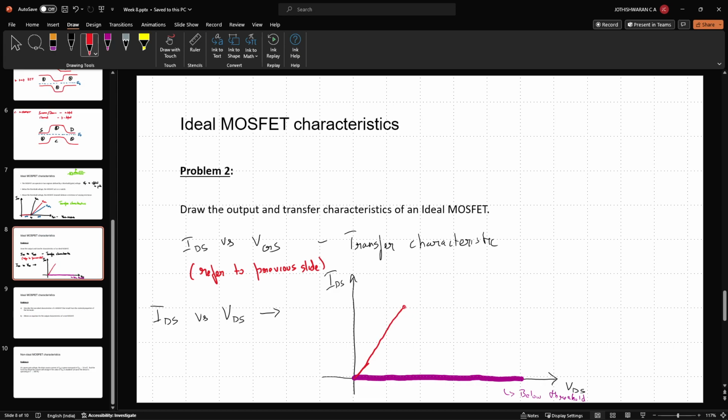After a certain point, the thing is, we are talking about semiconductors, where the amount of charge carriers is essentially small compared to metals. So we wouldn't expect this device to keep supplying current no matter how high a voltage we supply. Current saturation is something that is commonly observed in semiconductors.